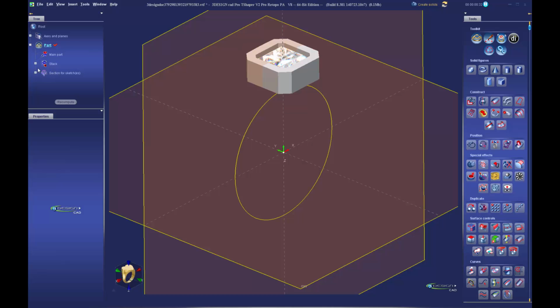If you have Delete Empty Elements on, it'll get rid of that empty part that we just started with. So there's our stack with the stone, the original sweep. That sweep we don't need anymore. You can delete that. It's still part of the history of our model. So unless you need to go back and completely change the sweep, don't need it. So there's the model that's already been converted. Our finger size, our ring size builder is still there.